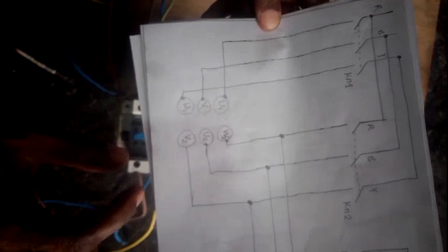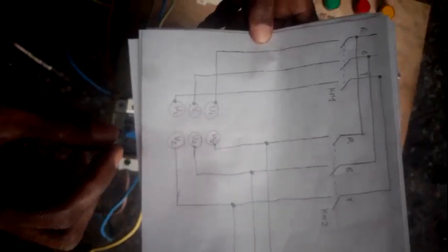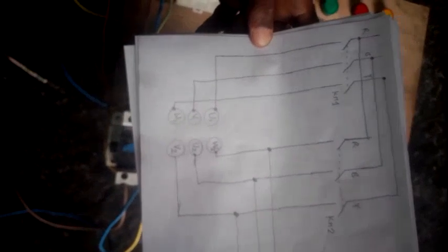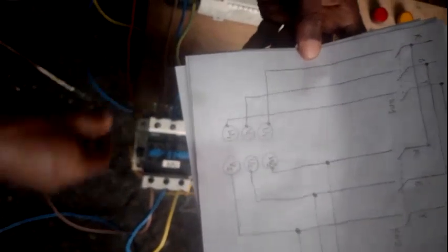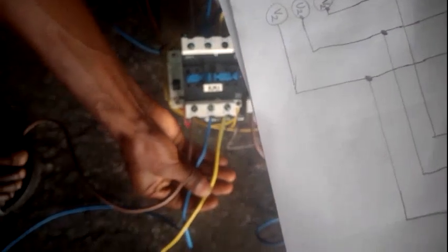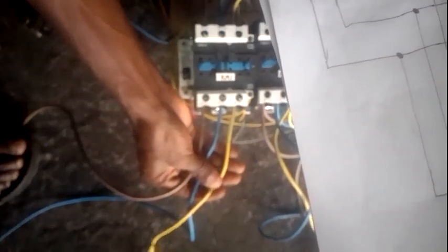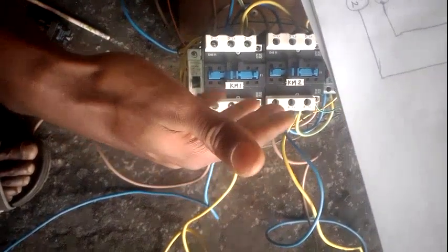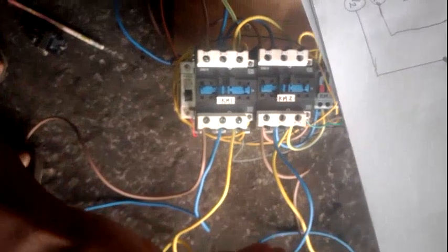It's a star delta connection. So in a star delta connection, the motor terminal has to be 6 connections. If it is delta or star alone, you will be dealing with 3 connections. So this is the 3 cables going to the motor side, to the first 3 connections of the motor terminal. Then the other one comes from the delta connection. So you see this connection, see this one, the delta contactor is looped. The input is looped from the input of the main contactor. You can see it here.